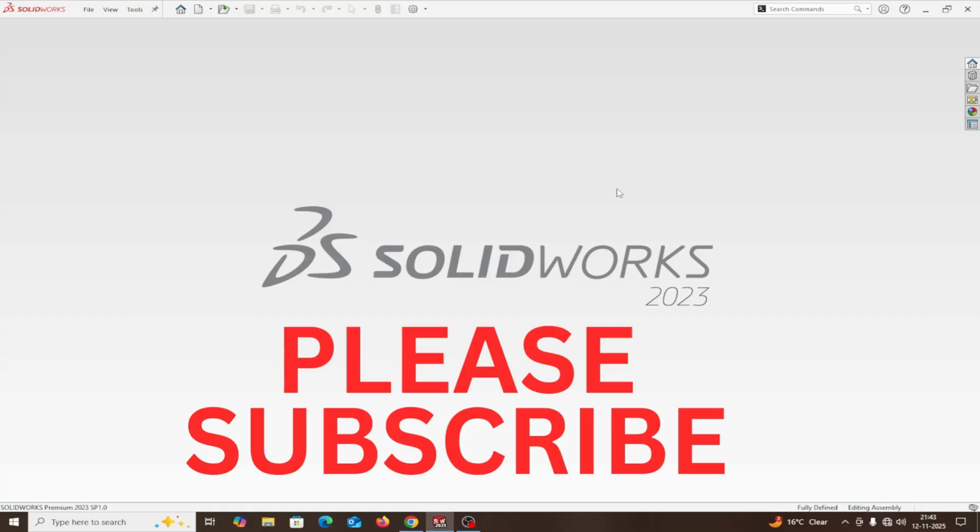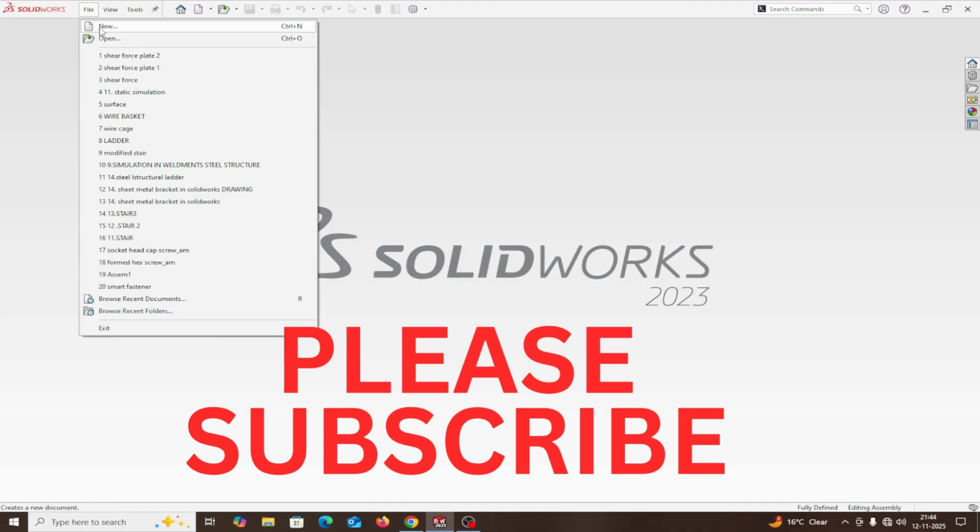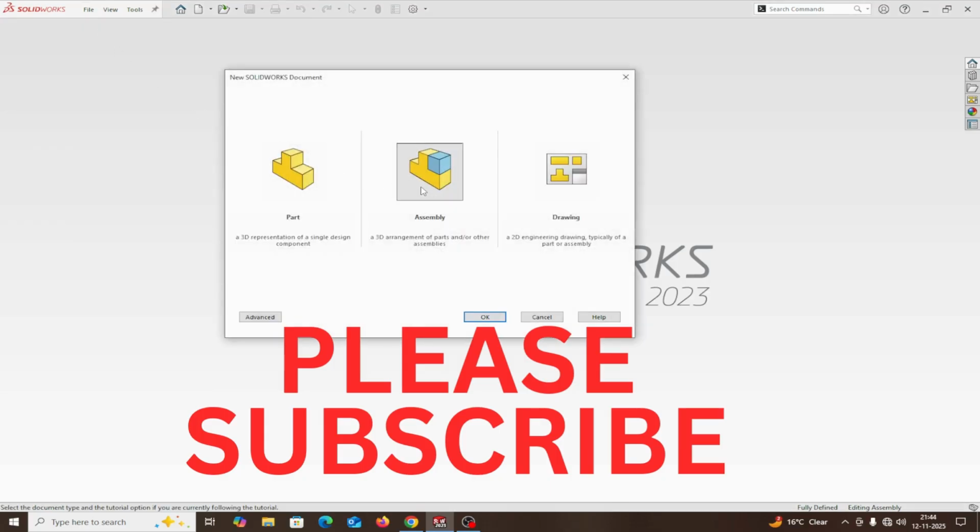Hello everyone. In this SolidWorks exercise, we will calculate the shear force in two plates which are connected by bolts and nuts in SolidWorks Simulation. Okay, let's start. File, new, assembly.